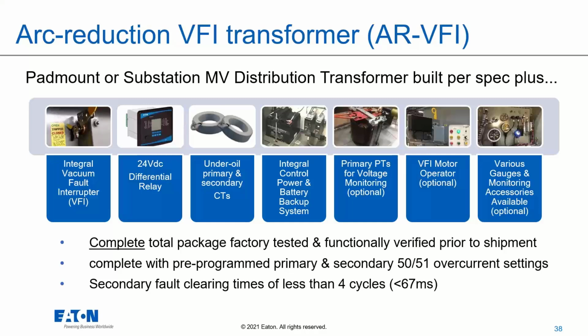Some of the other optional pieces that aren't always included but can be if a customer requests it are primary PTs for voltage monitoring, along with a motor operator for the remote actuation of the VFI. So that is something that we would mount on the VFI or the external handle, and it would be wired up to the control box and have convenient features for the user to be able to easily re-energize or de-energize the transformer with just the push of the button, and all this being located outside of the main compartments or cabinets on the side of the tank.